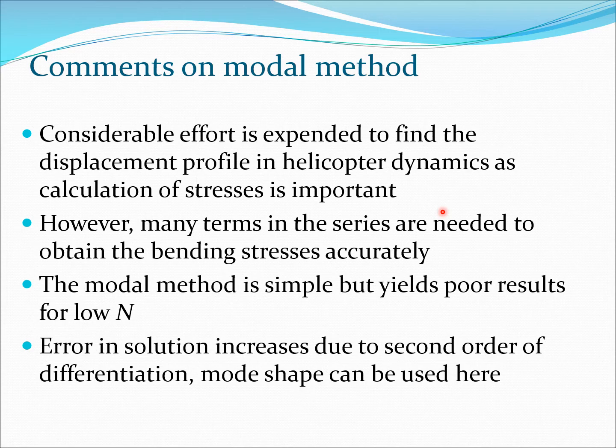Now let us look at some aspects about this modal method. First is that you are going to need many terms in this series to obtain the bending stresses correctly. So that is the sum over i is 1 to n, the value of n should be pretty large.